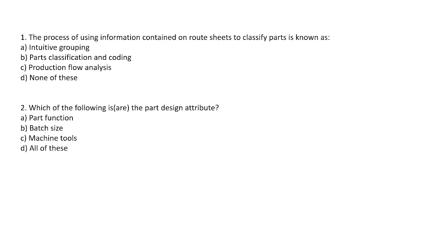The implementation of group technology can be divided into three different parts: actions on the manufacturing process, changes to the production process, and results for the organization. Group technology has set actions on the manufacturing process, that is part simplification, part standardization, and production control. Those are the three actions on the manufacturing process that group technology takes.